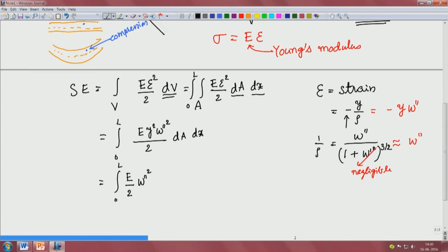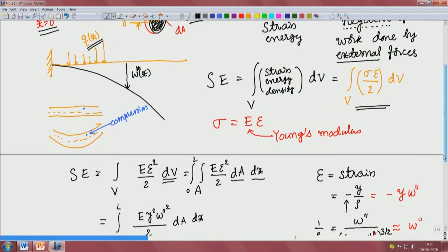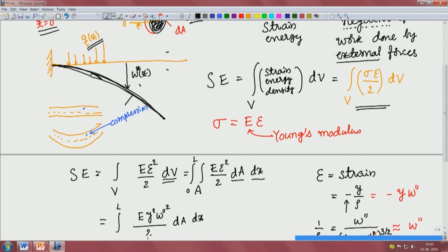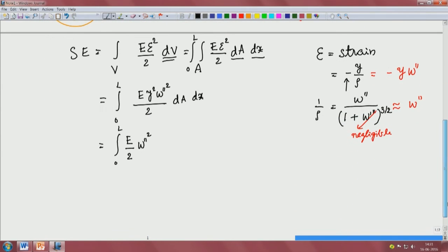In the one dimensional beam theory model of the 3 dimensional solid beam, we just have a neutral axis. So, if you take a slice at a particular value of x, the w there is the same. Across the width we do not say anything, all of that deforms like this, we are only worried about the neutral axis deformation. So, that can be taken out.